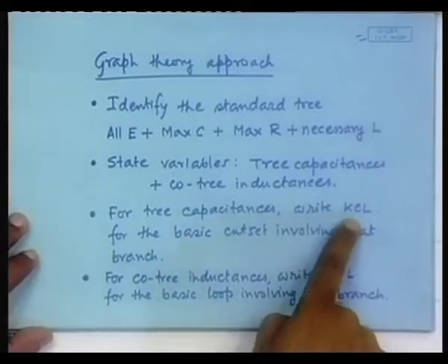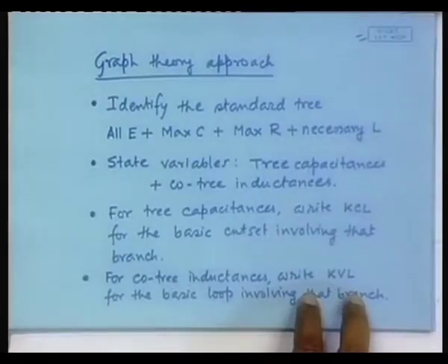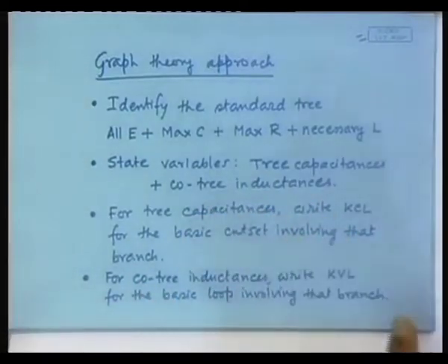When we write the KCL, Kirchhoff's current law involves the currents, and the current through a capacitor is C dV/dt, that immediately identifies the differential part. In the case of KVL, it will be the summation of the voltages, out of which one voltage will be the voltage across that inductor, which you substitute by L di/dt. That immediately writes the equation. Clear? So, that is the procedure, and we have seen its application in some very simple circuits.